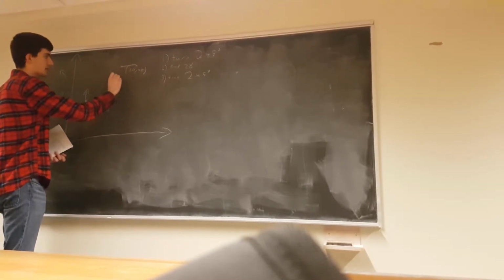So maybe as we're turning, we're slightly drifting off by an inch maybe. As we're driving forward, maybe while accelerating, the left side is able to accelerate a bit faster than the right side because there's a lot of weight on the right side of the robot. Now we're not driving perfectly straight for the first bit, which means actually we'll curve to the right a bit, and we won't even know it when we get there.